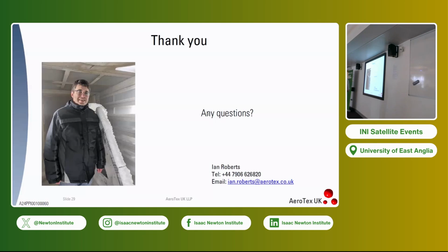Yeah. Well, it freezes on impact, so with rime ice it freezes instantly on impact, so it sticks, because most of the surfaces are aluminium. But at warmer temperatures it runs back a bit and freezes further out.